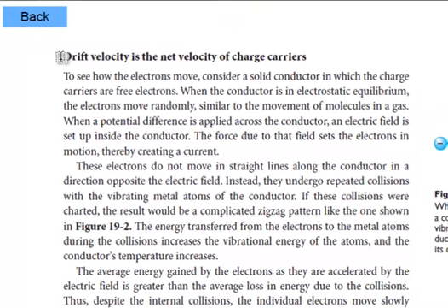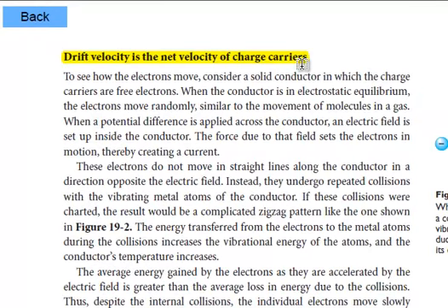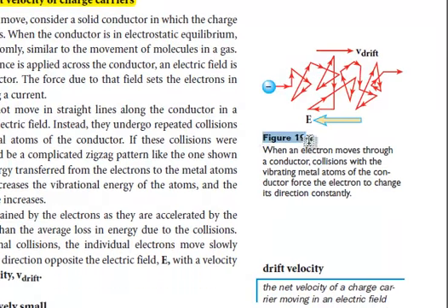The term drift velocity references the net velocity of the charge carriers, meaning every single one of these little arrows over here in 19-2, which are velocity vectors, could be very high. Problem is, you got a lot of positives added to a lot of negatives. The sum, or the net value, is actually not terribly great. So charges moving through wires have many collisions with the particles in the wires. And we talked about how the collisions generated increased kinetic energy for those atoms. It also generated friction from heat, and this is why electronic systems heat up so easily. And every collision provides a new velocity vector.